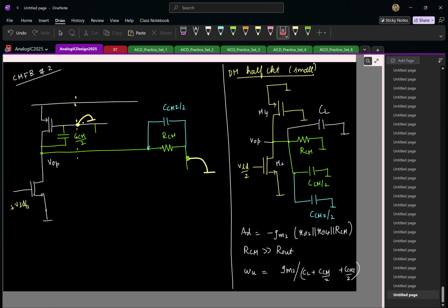So now as you see, in addition to having DC gain being dependent on RCM, even your unity gain frequency seems to be affected by these capacitors. So you can't go crazy and put large caps to stabilize the loops. Should be careful. So when you're designing for your differential mode omega u, these also have to be taken into account. Should have sufficient margin when you're designing for your differential mode gain, so that you can have some leeway for adding capacitors for common mode feedback, that is for stabilizing the common mode feedback. Is that clear? Great.